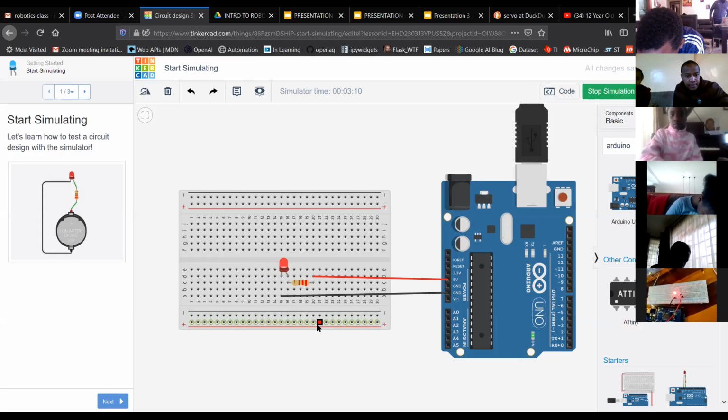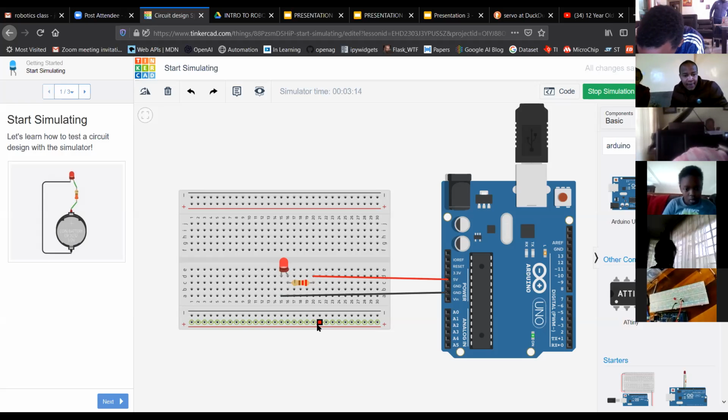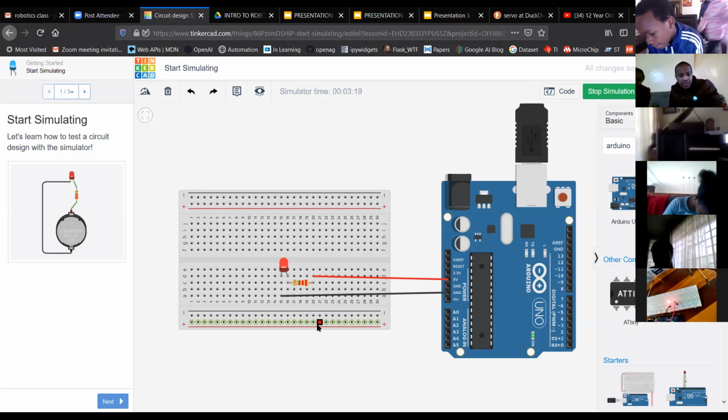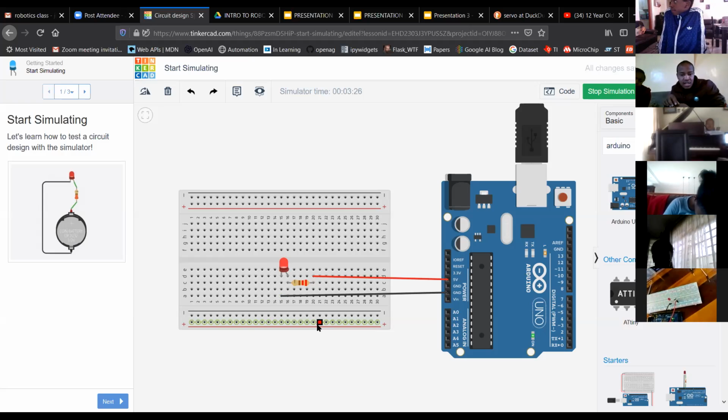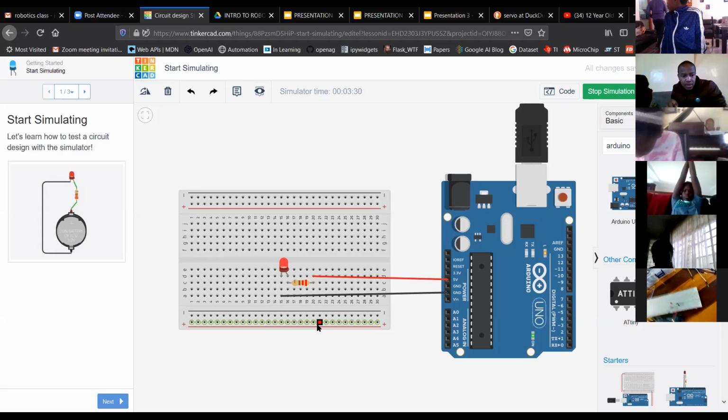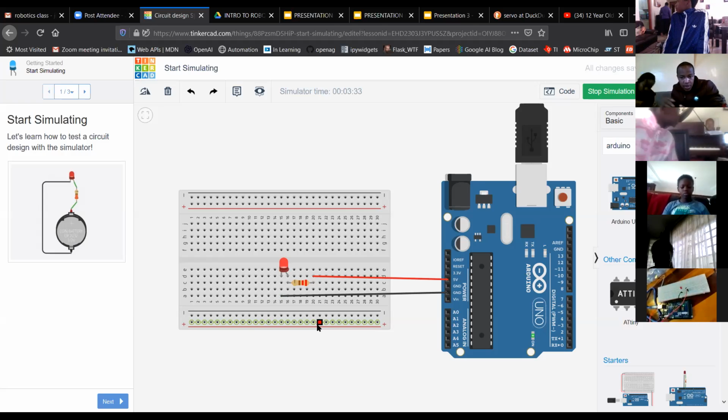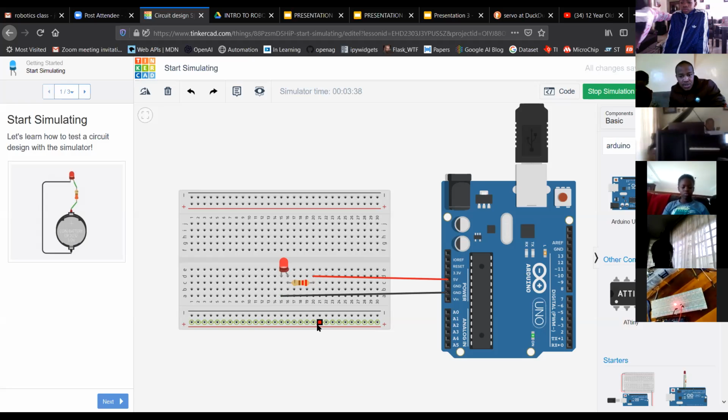Yes. Then now connect the black wire on the Arduino to GND. Yes. Then the red wire is on 5V. And also make sure you hold it straight so that you don't connect it to one and maybe when you look, it's connected to something else. So just make sure it's on 5V. Then once you've done that, connect the USB cable.